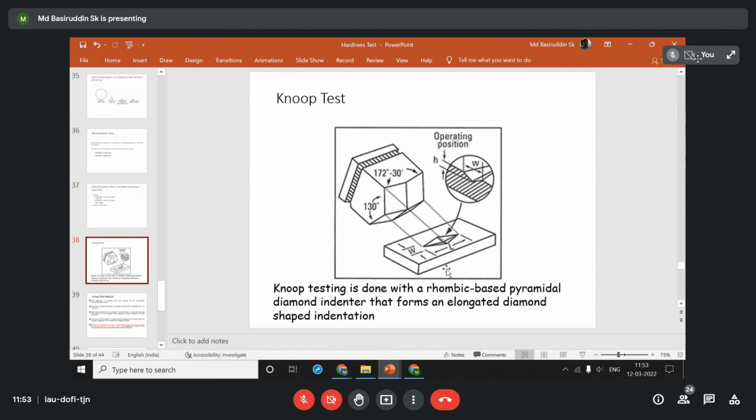So for the same material surface area, if we are able to take the maximum number of indentations, then that is the most correct approach. Another purpose is that if we put impressions having this particular shape, then we can encounter the effect of prior deformation. Throughout these impressions, we can intensively put plastic deformation on the material surface, because it is a penny shape, and the shape is not homogeneous. So the indentation is mostly restricted to the plastic region. That is the beneficial part.